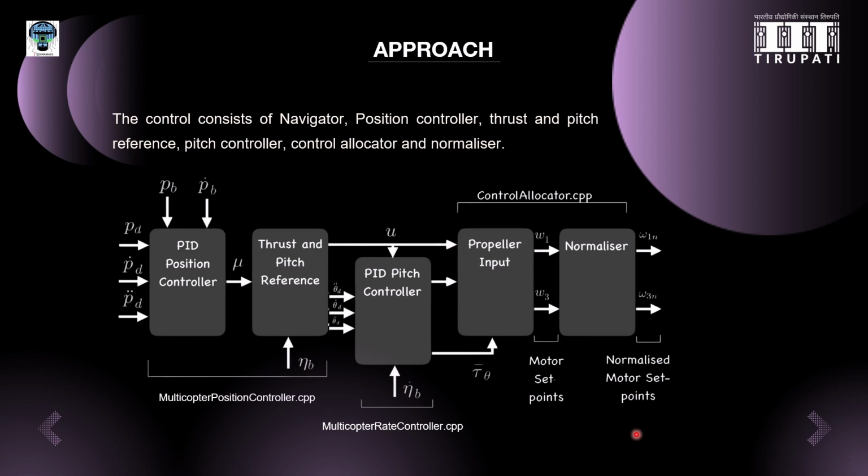In practice, we experimentally determine the PWM value needed to hover normally and use that as reference. All commands are normalized around that hover setting. We also impose rate limits so that sudden jumps in throttle are smoothed out.